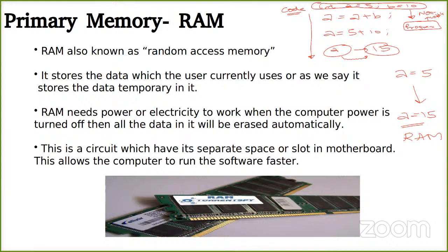All right. So this I will call my program memory. Int A is equal to 5 and B is equal to 10 are stored inside your flash memory if I talk of an embedded system. Once you store data inside your flash memory, that data is not erased even after the system is switched off. When we use an Arduino, you will understand that when you store the program inside the Arduino, even if you unplug the system and plug it on again, the program remains there. But what changes? The values of these variables keep on changing.